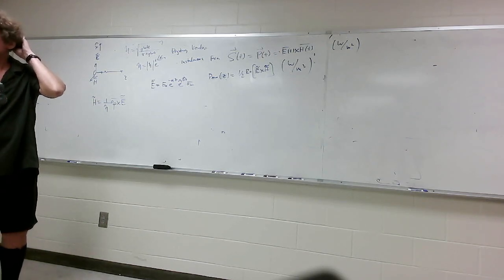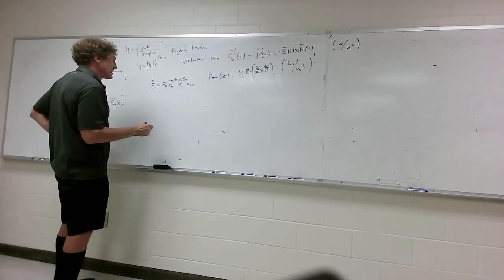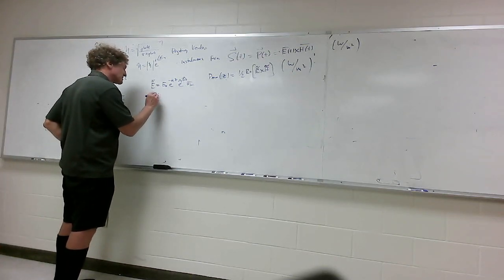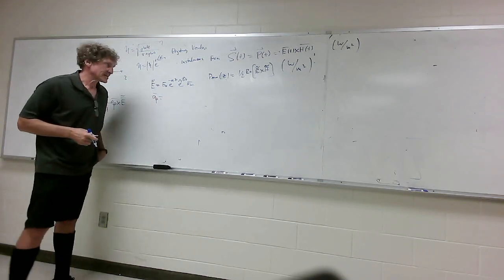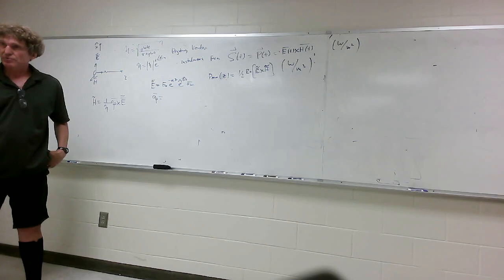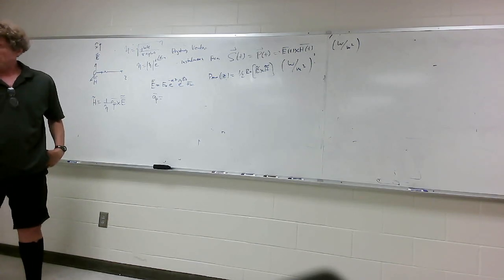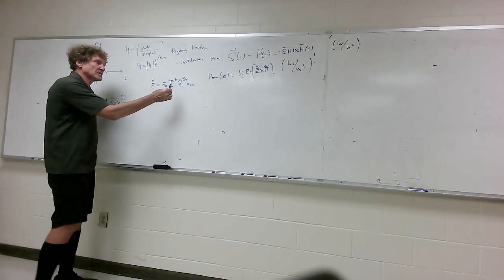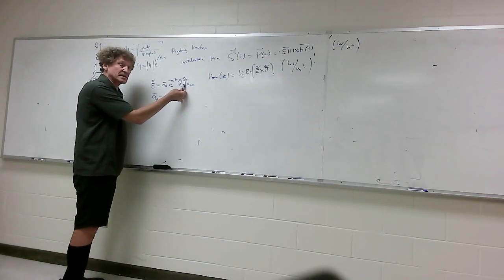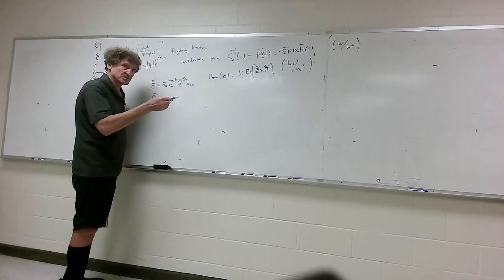Do you remember this? Now from that, if I want the direction of propagation, what is it for this one? Just by looking. Class? AZ. The unit vector in the direction of propagation is positive AZ, right? You determine that just by looking at this, because the z tells you that e to the minus j beta z, it's going in the z. The minus j tells you it's going in the plus z.